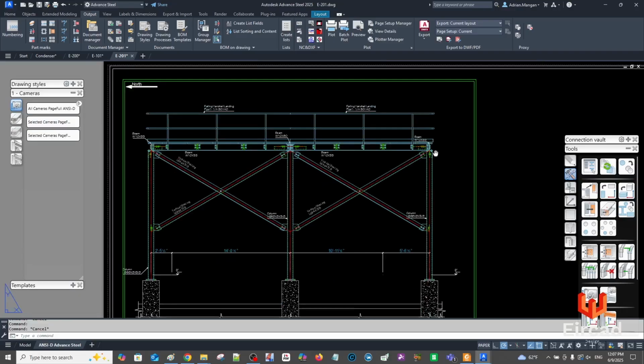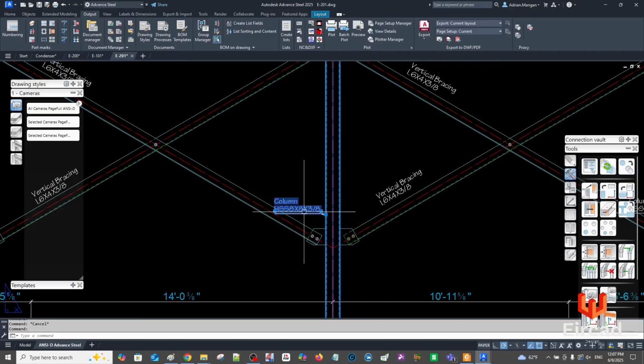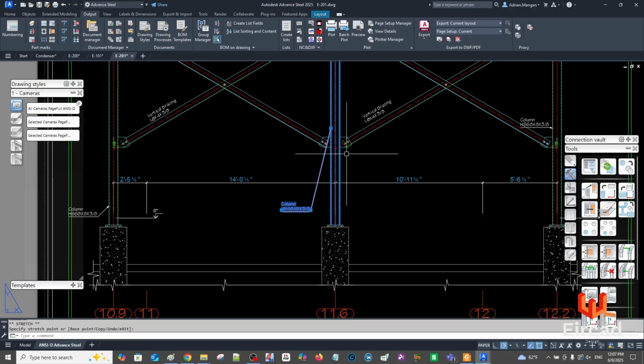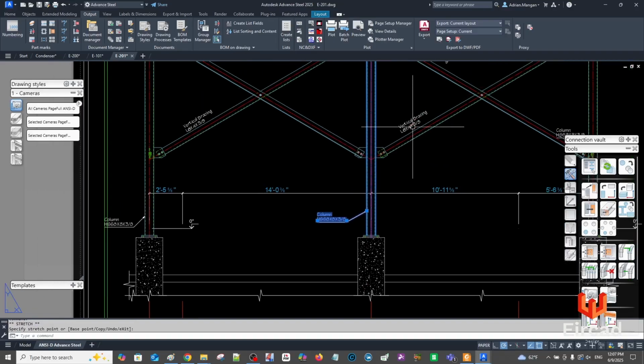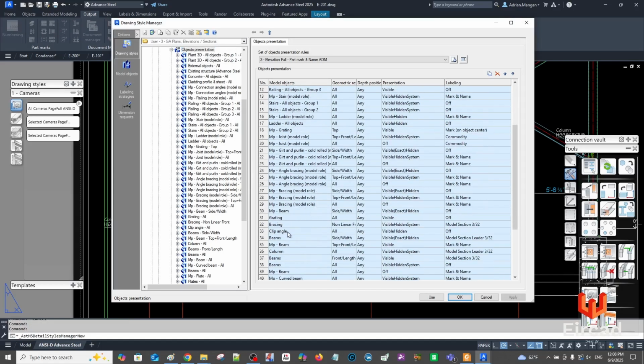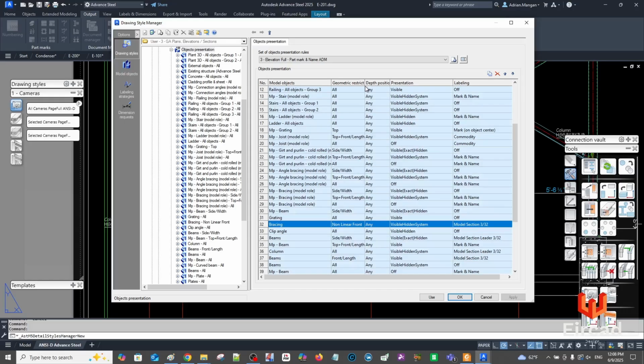The one other thing I might do is, remember we did this bracing? There's a couple of different ways of doing it. You could separate the two of them, or we set up this bracing where it'll just do the ones that are going across in front of you. So bracing, non-linear, front.